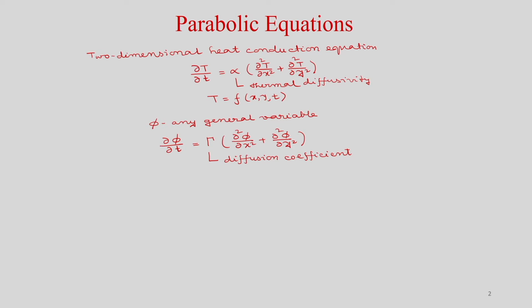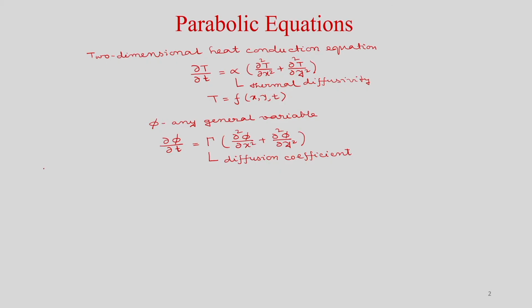Like in earlier lectures, we will consider first the explicit method and then the implicit method, and we will try to discretize this model equation. So, first let us consider forward time and central space, which is the explicit method, commonly known as FTCS. In the explicit method, you know that there will be only one unknown and we are marching in time. So, we will go from time n to n plus 1, where n is your previous time, n plus 1 is your present time, and this is your delta t, the time step from t n to t n plus 1.